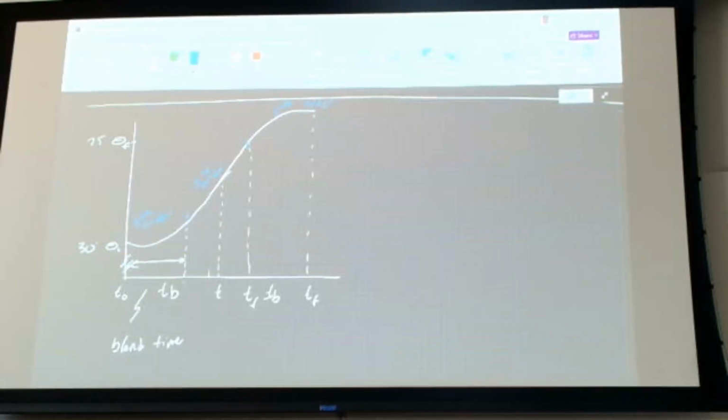And so during the traversal, we could consider this to maybe be more of a parabolic. This could also be linear and another parabolic. Even though it's parabolic, we're going to take it to a fifth order, so we have very good control.